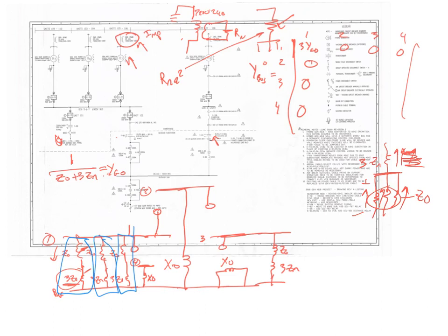Okay, so are we ready to build the Y bus? Continue. So we look at bus 2. All we have is this transformer. What is that? T85. So this is going to be Y85-0. And then that's it, right? There's nothing else connected, so that is going to be 0 and 0, 0 and 0.